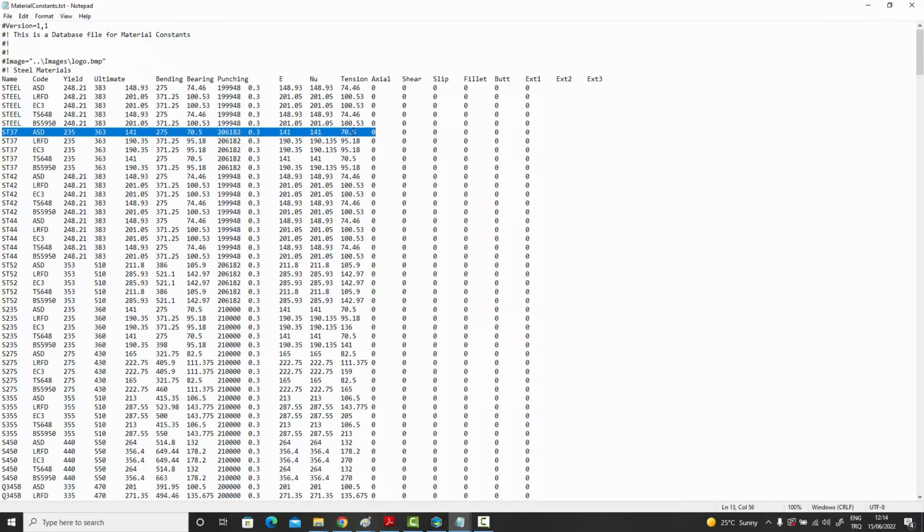So if that is the number, it's going to multiply that by the shear area of that beam, and find out the capacity of that beam, and then it's going to say whether the number of bolts are working for that or not. And like I said, these numbers will not appear on your reports. These will only be used in that preliminary design, which the macro quickly does to find an approximate number of bolts, thickness of plates, and weld sizes.